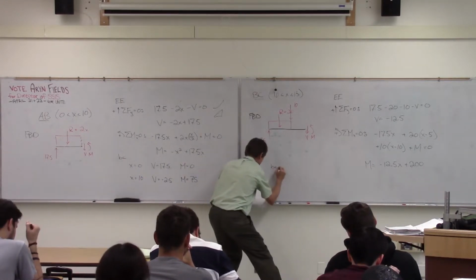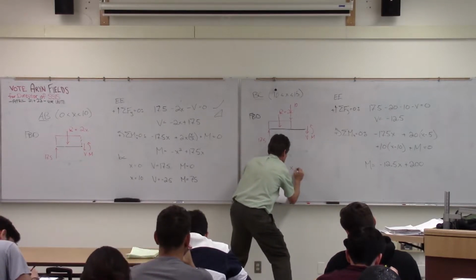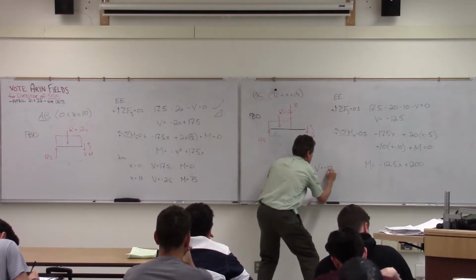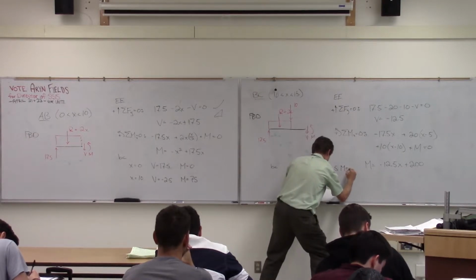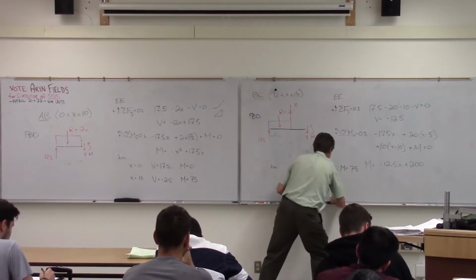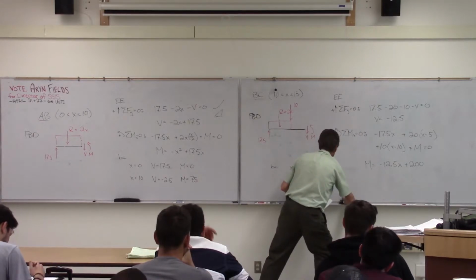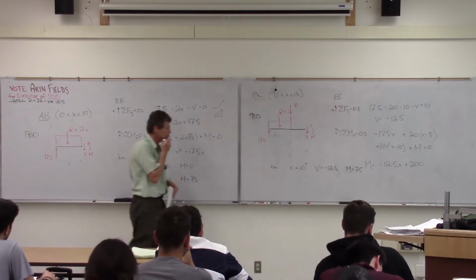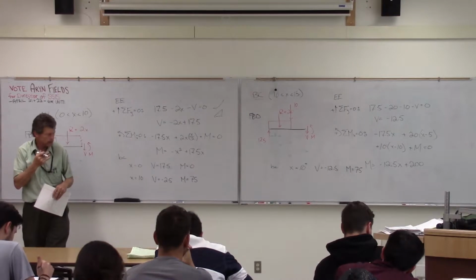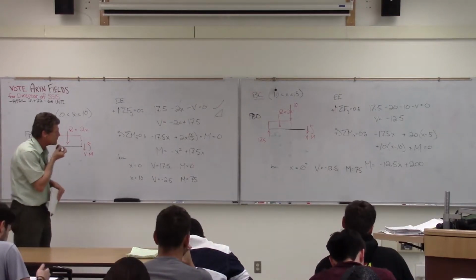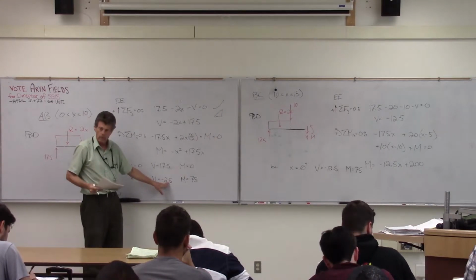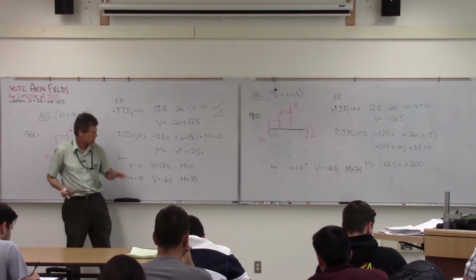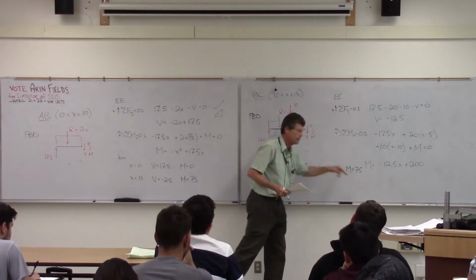Boundary conditions, and if you want to call it 10 plus. Okay, so just past that 10 there, what we find is then our shear changes from 2.5 to 12.5, and our moment stays the same though. It's 75 here, and it's 75 here.